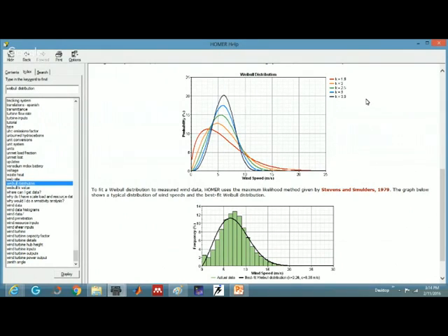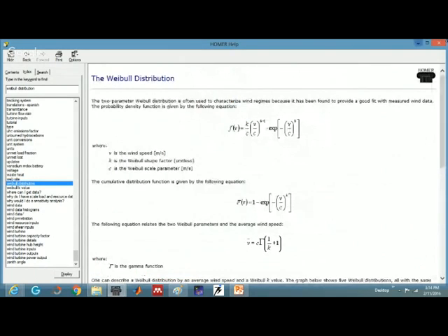And most of the time we don't even care about the general Weibull function. When we take k equals 2, we talk about Rayleigh functions. So the Rayleigh function is one of the best for a wind turbine location. If the wind speed graph is like the green one in the k plot, the third one from above, this is the best location to install a wind turbine. So that's why we do all this data analysis.